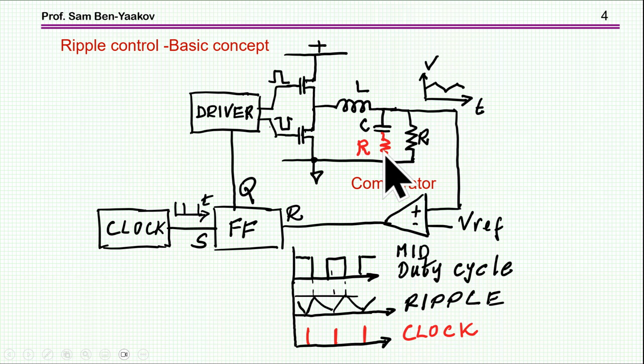So here is a basic LTspice schematic that shows this concept. This is a generic set reset flip-flop. The output is 1 volt here. This is just the basic module. I have a reference of 1 volt. The output has a divider 4 to 1, so basically the idea is to get here 5 volts. This will be 1 volt here, which goes back to the feedback. So this is now the comparator.